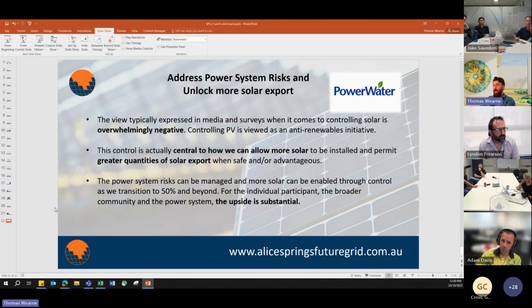They can create reactive power, or in this case, it's generally absorbing reactive power to achieve a voltage effect. What you can think about it doing is it sucks in power that's at unity or whatever it's in, and then puts it through either an inductive or a capacitive stage to shift the voltage and current waveforms, and that's going to have an impact on the voltage. So it performs the function of a voltage regulation service without needing any load or any power on the panels for that to work. Yeah, it's more basically a filter.